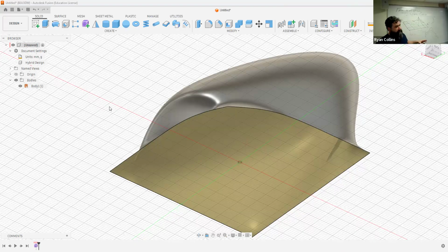We will do some more work with putting in some dimensions, some thickness, adding some actual function to this in a moment, but I just wanted to walk you through the extreme basics of the Form Workspace, just knowing how these tools function. The main tool is your edit form. That's the one that really lets you morph things around individually. How to fix an error of self-intersecting faces, and how you can go back and forth to finish form, which brings you back to the solid parametric modeling workspace like we've been working with all semester.